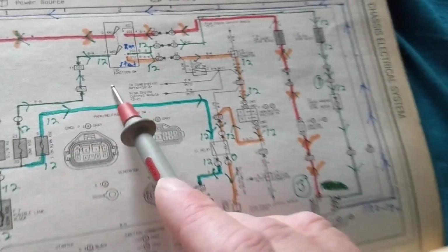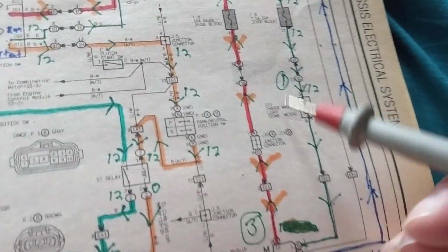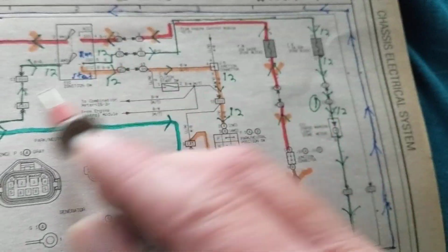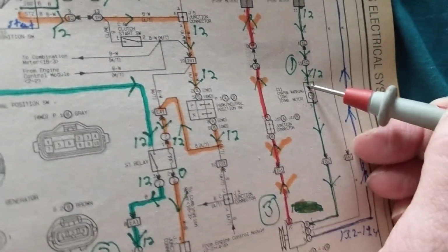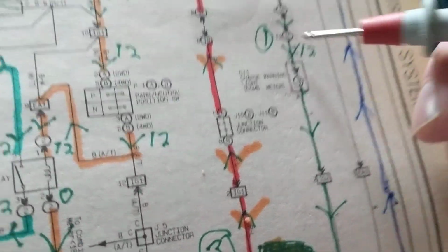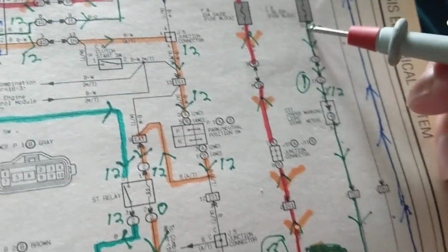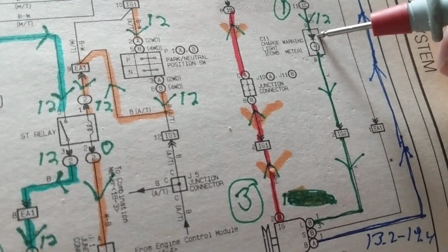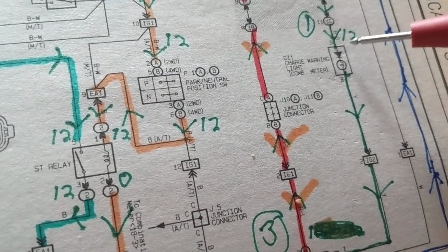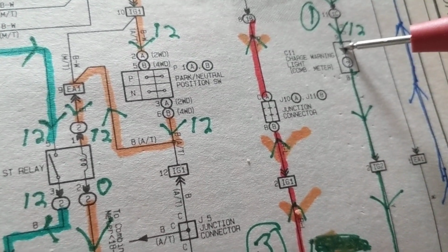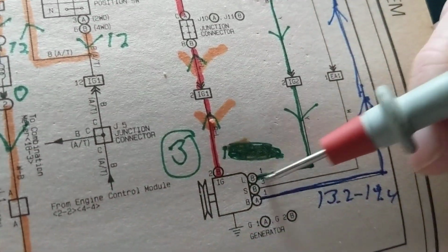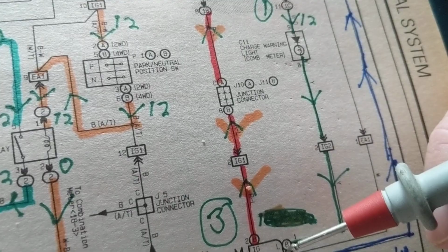So, with that, number two, we said, what's the diode for? The diode is over here to make sure that the battery is connected correctly. A diode can only work in one direction. This is called the anode, and the other one is called the cathode. Anyway, this is a protection device to make sure that the positive of the battery is connected to this. If the negative is connected, this will not conduct. This will only conduct one way, when the positive is connected to this anode. If I flip the battery cables by mistake and I put a negative, guess what? We're going to save the alternator from damage. That's its purpose.